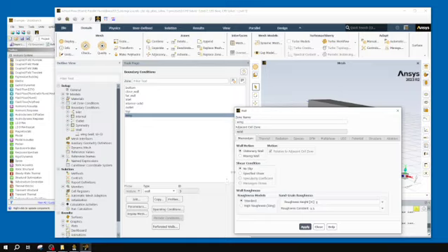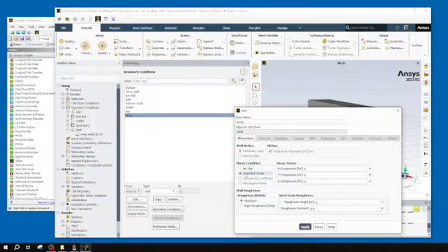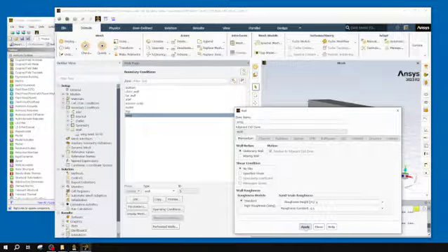You do have this specified shear, in case you wanted an object that had, I don't know, a certain shear stress on its surface, let's say you're simulating an experiment where you already knew the shear stress, that can help make it a little more accurate. But we are going to want this no slip condition, and it's going to be a stationary wall because we're considering the wing moving through air by making the air move, not making the wing move. So I'm going to apply that, make sure that is all good.